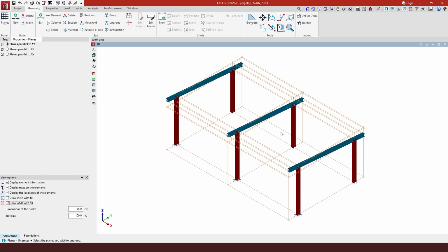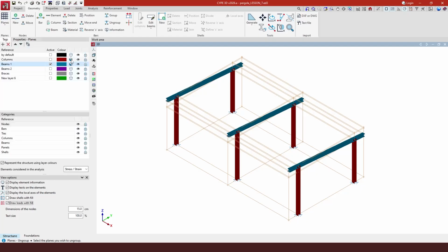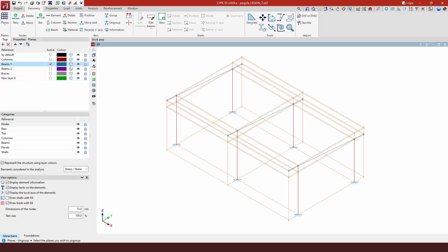Okay, for this next step, we're going to insert the beams in the roof. First, we're going to come to tags and we're going to make these ones just segments, not the 3D view. Remember, we explained the first column, the icon of the duck. This third column is a lock. So if we lock any layers, they will be snappable, which is very useful sometimes also for the selection. Now let's select as the active layer the beams 2.